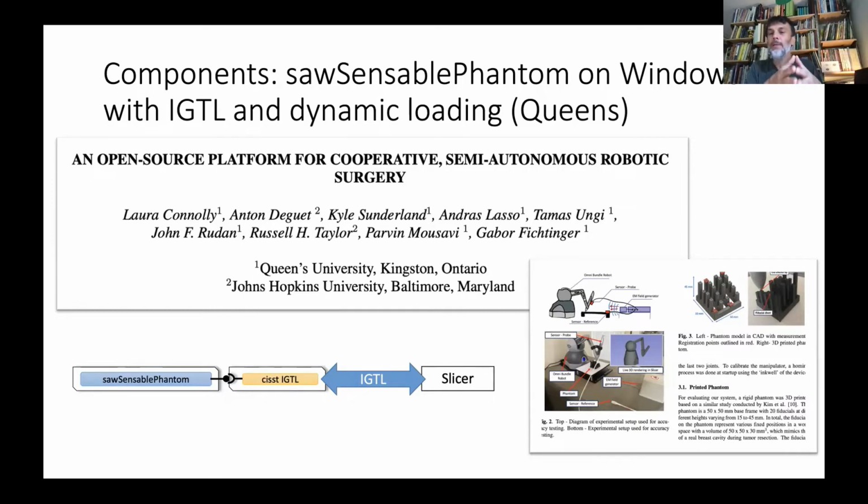So right now I can run the dVRK on macOS with IGTL, but with ROS2 being technically portable across different operating systems, we might have a Windows SO component with ROS2 bridges. I'm not advocating for it, but if you have a hardware requirement for a driver that is only available for Windows, which some vendors still do, then that becomes really valuable.